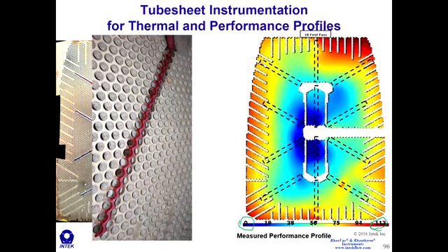One way I like to look at these is to identify the yellow color, because it's easily identifiable. Yellow corresponds, for this particular plot, to about 75% cleanliness, and you can see the boundary that it draws around this area, which is an area that's affected by inundation and air in this particular condenser. Now, inundation won't get you down to 0%. This is really the effects of air binding in this region here. So here, here, and here, these are all air-bound zones, and this in here is the air removal section. This is a stagnant zone here.